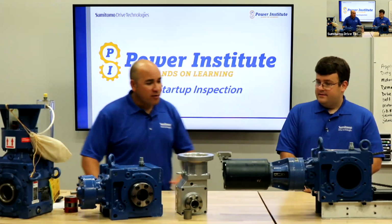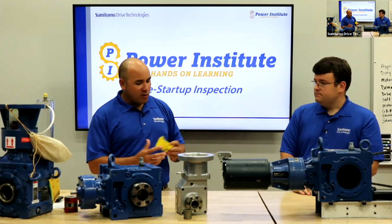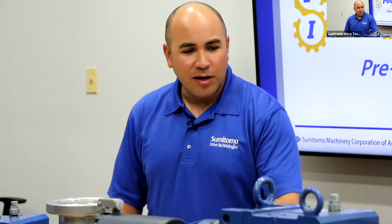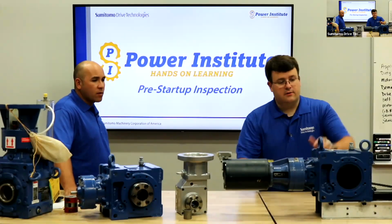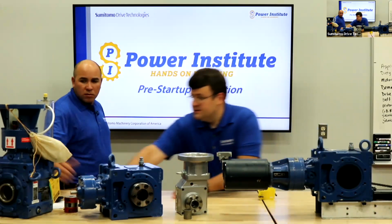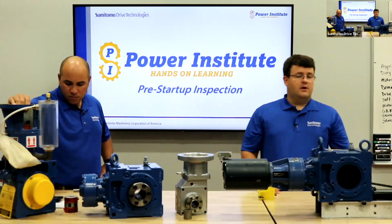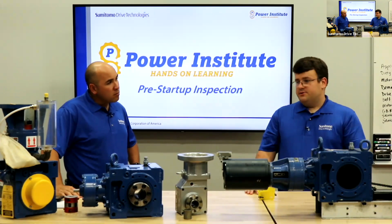So I've got a couple of questions. We've got some guards and things here. I assume we need to make sure we've got all of our correct safety equipment, guards, anything else that's needed. Right, on the gearbox side. So these are the high-speed guards here. There'll always be a low-speed guard. Actually, if you spin that one around, you can see there's our low-speed guard there. Make sure those are all guarded. Chain and sprocket, sometimes there'll be an entire guard over that. You want to make sure you have that.